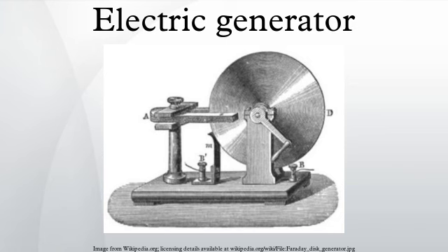Terminology. The two main parts of a generator or motor can be described in either mechanical or electrical terms. Mechanical: rotor, the rotating part of an electrical machine; stator, the stationary part of an electrical machine. Electrical: armature, the power-producing component of an electrical machine. In a generator, alternator, or dynamo, the armature windings generate the electric current. The armature can be on either the rotor or the stator.